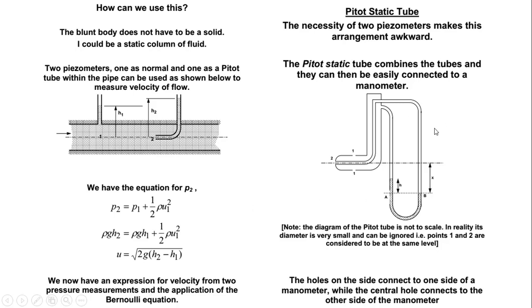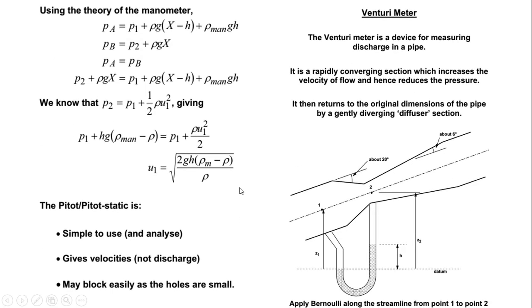Okay, the other thing that we can do is use piezometers to work with our pitot tube. We can connect zone number 1 to this part, which is subjected to pressure here, pushing pressure down this side, and zone number 2, which is ambient pressure, is also being subjected to this side. So for this X that we have, using the equation that we worked with for manometers in statics, we can find this pressure increase using the manometer. So if we work with manometers, we can also find our U1 using the manometer reading that we have here.